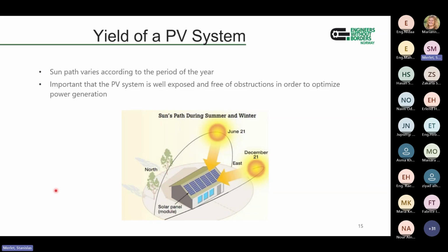Everything is about balance always, but it is a balance to find between wind loads. So mounting your modules horizontally or vertically, for example, that would have a lot of wind loads, and then you would need a very strong system. It exists. We see that especially in the kind of mixing solar PV generation and agriculture, for example. So that allows agriculture in between, but then the system is way more robust and a bit more expensive.